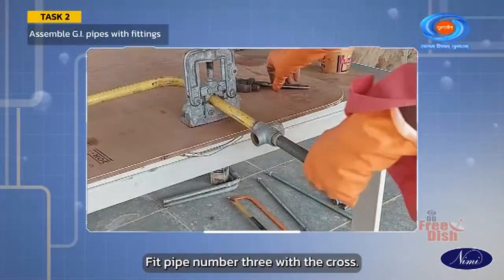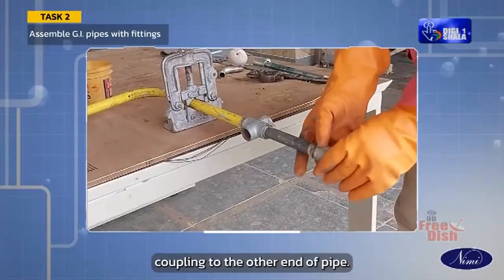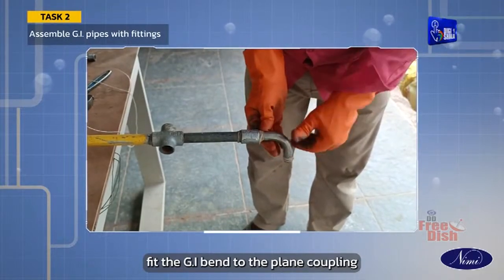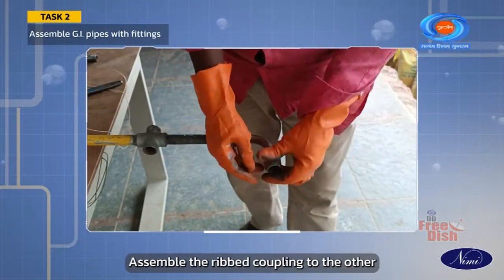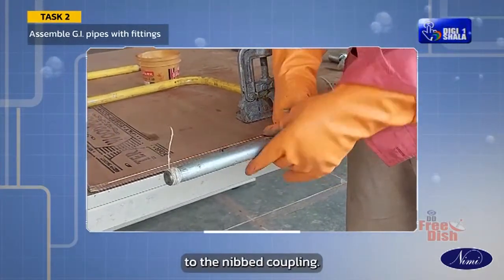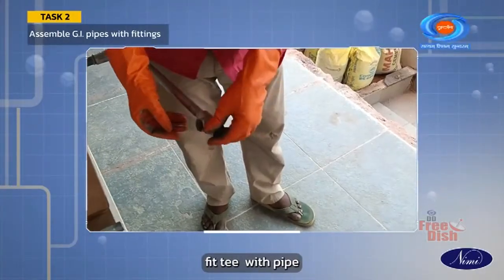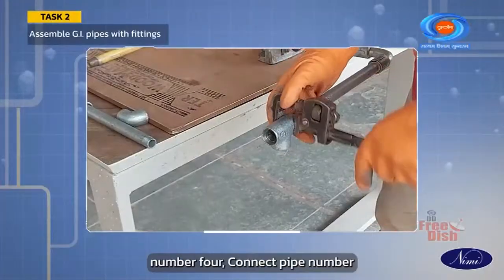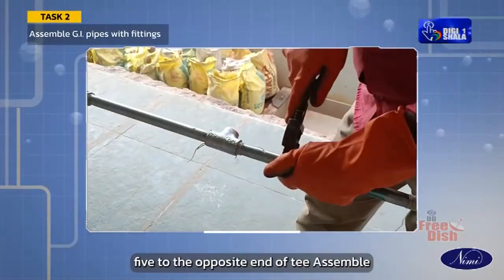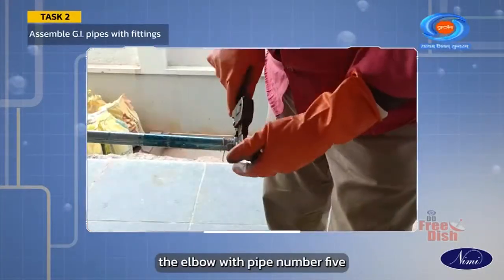Fit pipe number 3 with the cross. Join the plain coupling to the other end of pipe number 3. Fit the GI bend to the plain coupling. Assemble the ribbed coupling to the other end of the GI bend. Connect pipe number 4 to the ribbed coupling. Fit T with pipe number 4. Connect pipe number 5 to the opposite end of T. Assemble the elbow with pipe number 5.